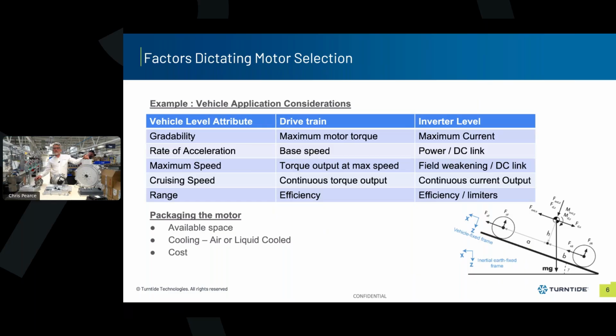Just a note here on some of the points about motor selection is around packaging the motor. Motors come in all sorts of form factors. Are you going to be using liquid cooling, air cooling? Airflow around the power electronics is a critical part of that, and all constrained by cost of the final product.